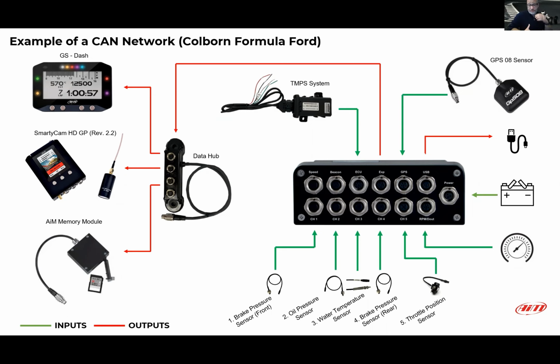This is actually mine. Some people may be wondering why I've got the battery indicator as an input. It's interesting that when you run a Formula Ford, and I'm sure the same thing potentially applies to things like karts as well, although I'm not a karter, so you can tell me if I'm right or wrong, I've had instances where the battery hasn't charged properly before I go out to a session. If you know what your battery's voltage is that's powering your device, you can log that and have a warning on your dash that says your battery's low. We've had to either replace a battery, or we've found out the battery was fine and the charger was broken.